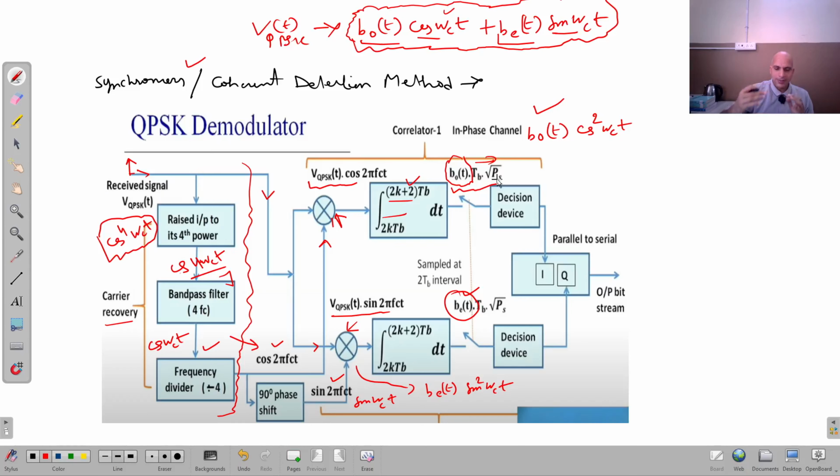So obviously it is a variation that can be positive or negative. We know very well that this odd bit can be positive, can be negative. Similarly, this bit can be positive, can be negative, because we have used the bipolar NRZ that converts 1 into +1 and 0 into -1 volt. So according to that, whatever bit stream is coming here, we will get some voltage, and then that voltage is applied to a decision making device whose threshold value is taken as 0.